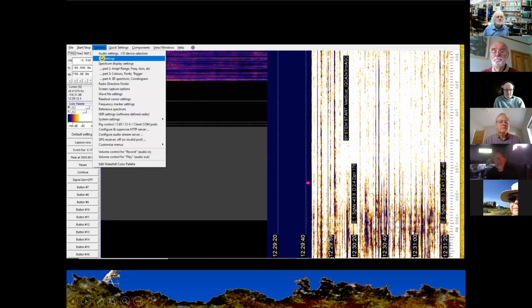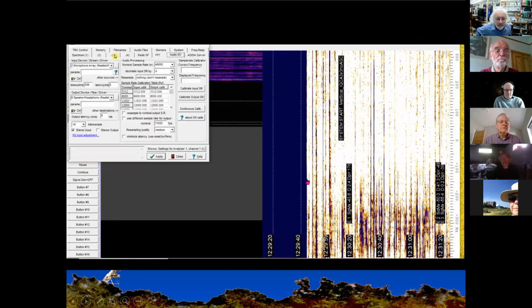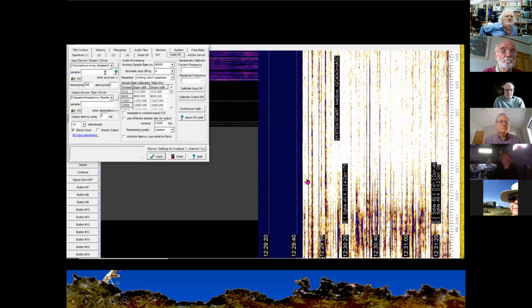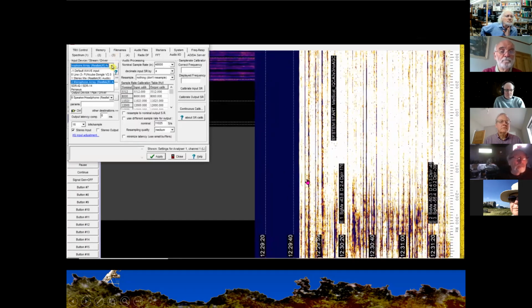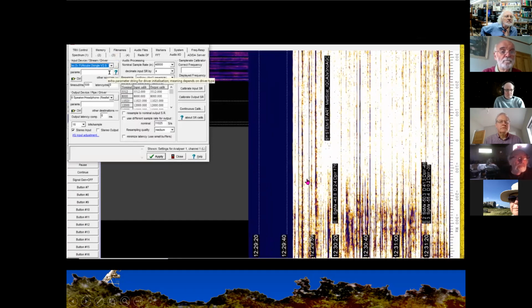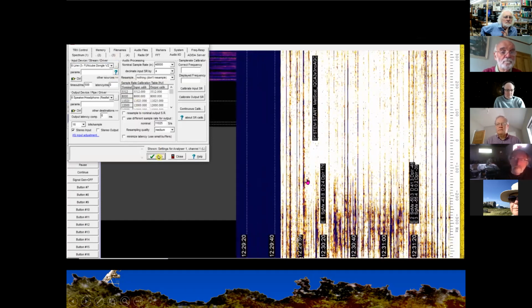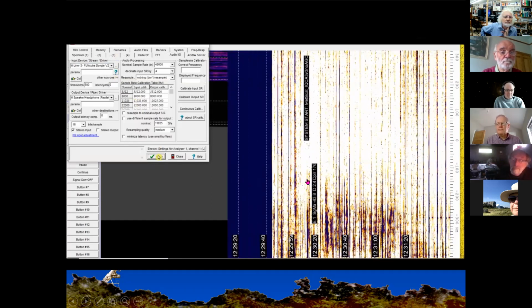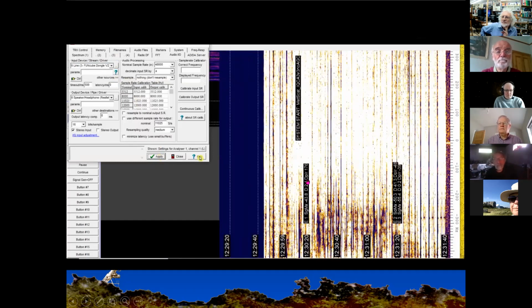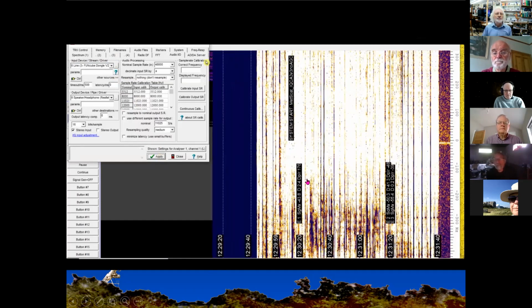This all looks a mess because we're actually still looking at the microphone inputs of the laptop. So I'll go into Options over here, and I will go into Audio Input, and instead of the microphone array, I will choose the FFT dongle SDR receiver that I use for Meteor scatter work, and apply that. And sure enough, we start to see the signal from the FFT dongle.